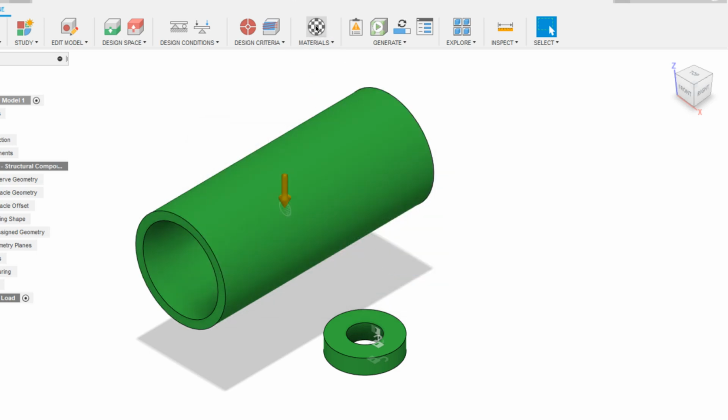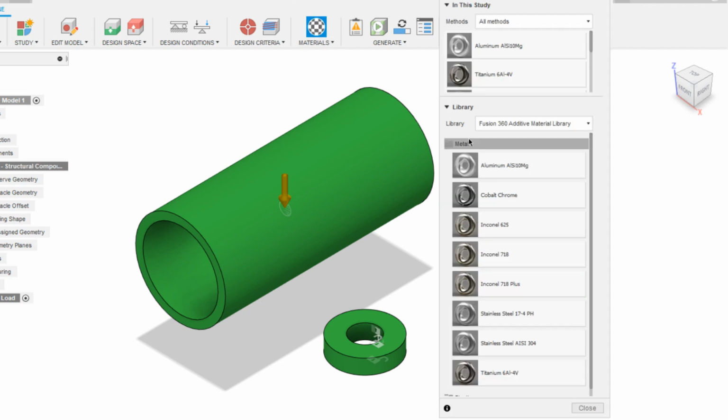and if you click on materials, if you go to die casting, you can see a calculator button next to the material. For this material it is not having. Similarly for the other materials, I'm just gonna right click and delete those. For those not having the calculator button, which is cost estimation.